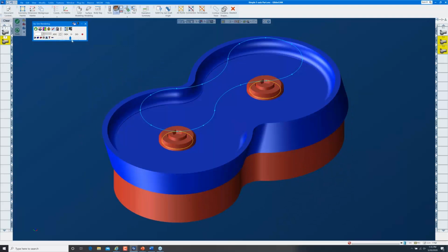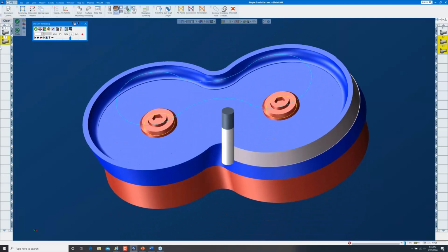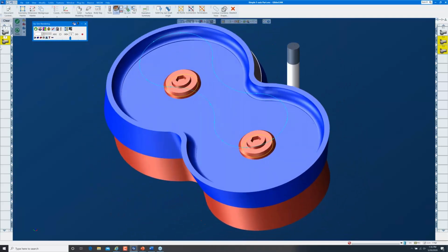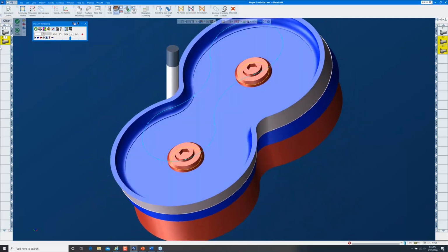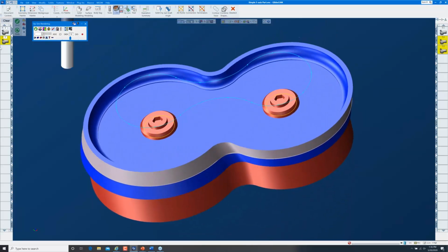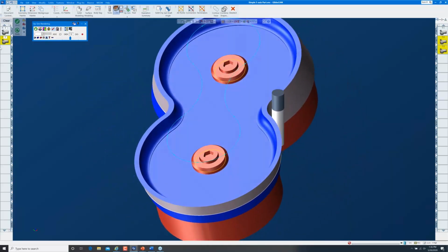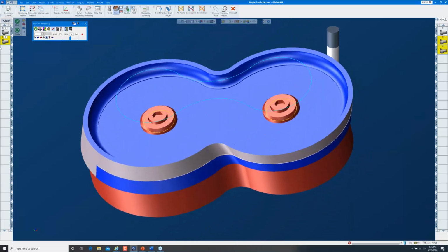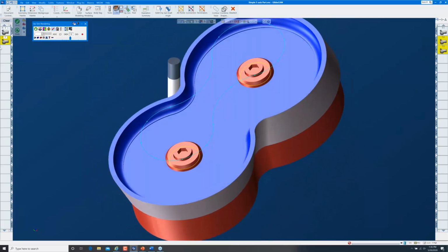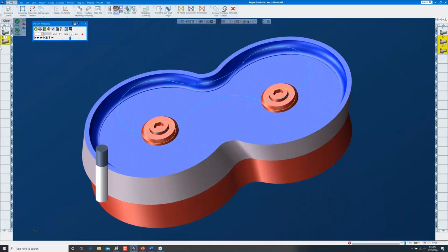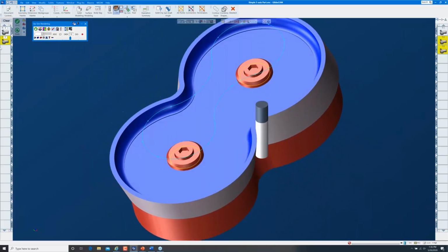All right, in the last half hour, 35 minutes or so, we haven't gotten in a rush. We've taken our time, and yet we programmed a 5-axis finishing pass on the undercut radius. We tweaked that toolpath. We tweaked it again to provide gouge avoidance and developed roughing and finishing toolpath for a score profile. The task associated with developing these toolpaths is laid out in a simple, easily understood manner. It makes it easier to learn, it reduces the programming time, and lessens the risk of mistakes.